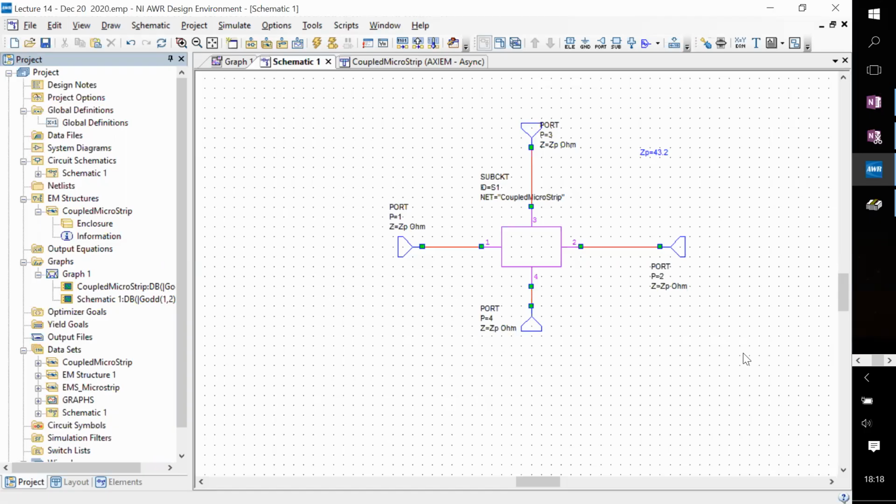But yes, when I define in Microwave Office to measure gamma odd or gamma even, it's a special kind of excitation and a special kind of measurement, which is happening simultaneously on 2 ports at the same time.